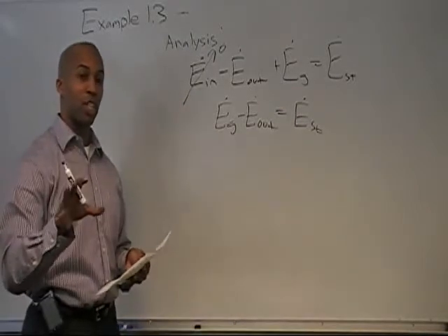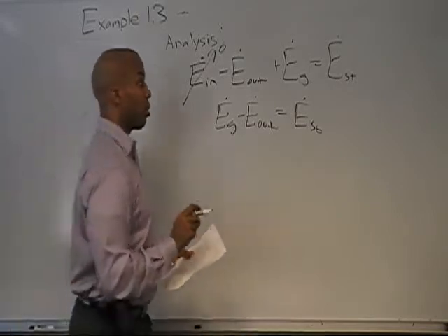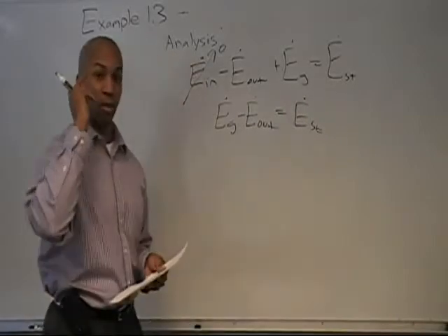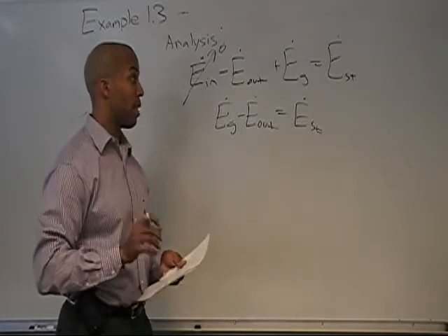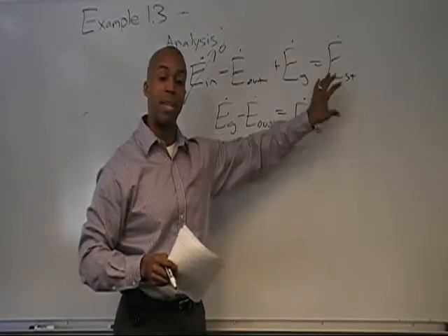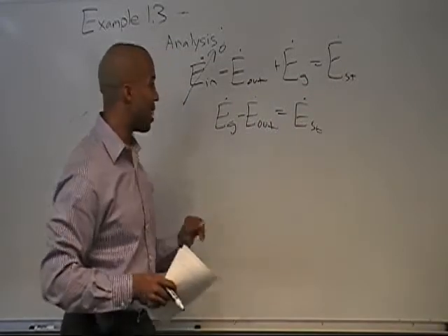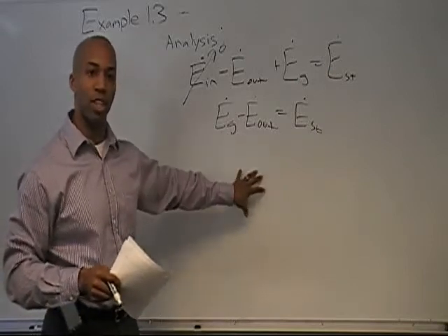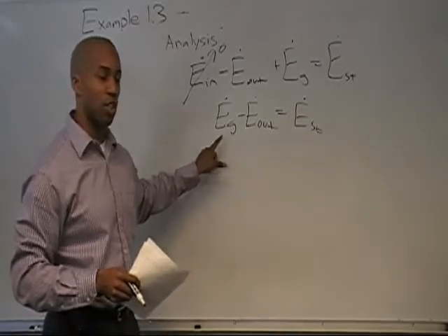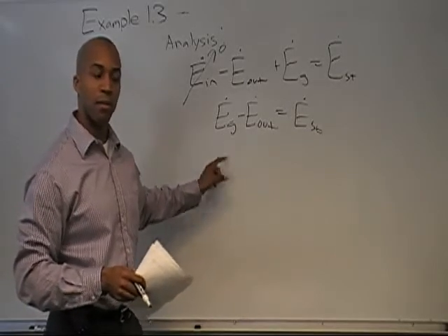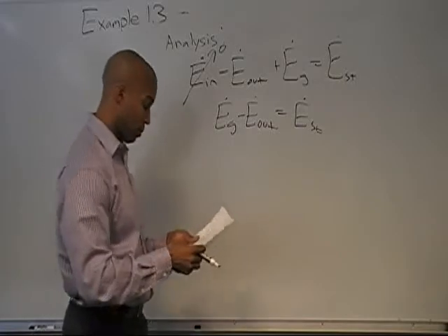Now we're on a mission to find a relation for the change in temperature with time. Some of you may remember earlier in the lecture what the energy stored looks like, and there's a derivative of temperature with respect to time. So we're going to be working with this equation and manipulating it by representing the stored energy as we did before, and then inserting the appropriate rate equations to characterize the energy leaving the system, and then representing the energy generated by way of the electrical heating with an appropriate relation.